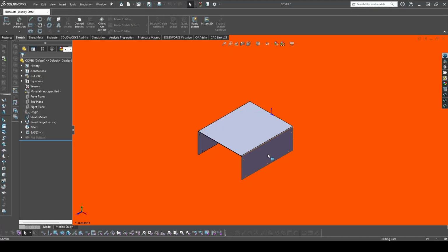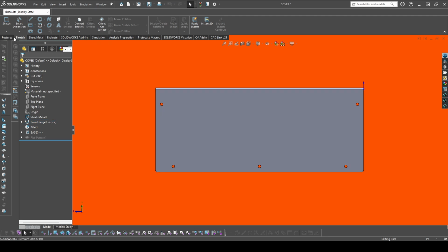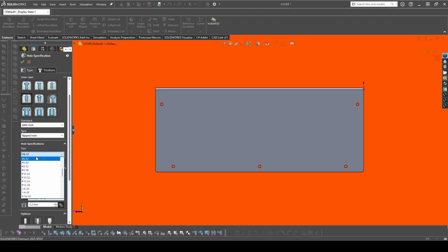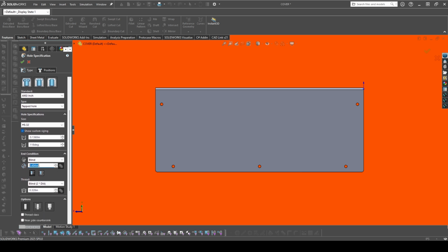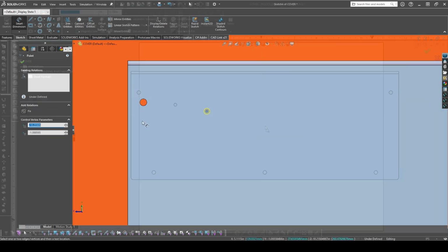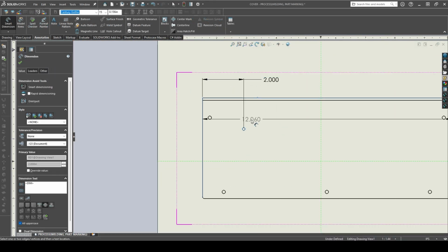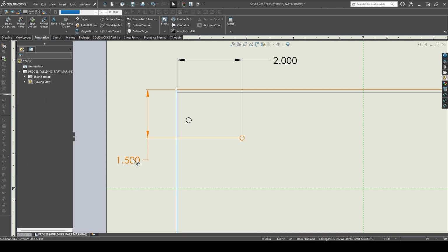So in SolidWorks, instead of manually sketching and dimensioning every hole and feature, utilize SolidWorks' Hole Wizard and standard feature tools. These often come with built-in tolerance schemes. For example, when creating a tapped hole using the Hole Wizard, you can select a standard thread size and class. The associated tolerances are usually well established. When adding dimensions, don't just accept the nominal value, use smart dimensions and explore the tolerance options in the Property Manager. You're going to want to select the dimension that you want to tolerance.